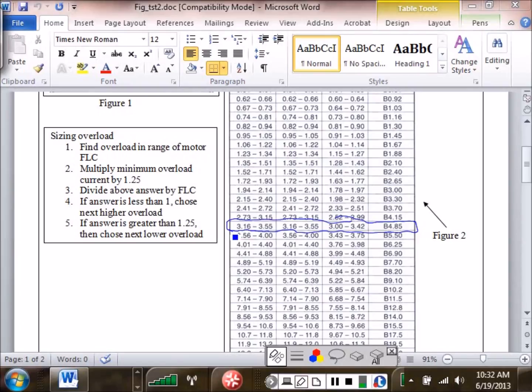So say my load is 12 amps. Well, there's no such thing as a 12 amp circuit breaker. So I've either got to go down or I've got to go up, because circuit breakers are sized according to short circuit, right? You understand? So depending on what we're looking at would depend on whether I'd use a 10 amp or a 15 amp breaker. So sizing your breaker is pretty critical. So I'm looking at this one right here.